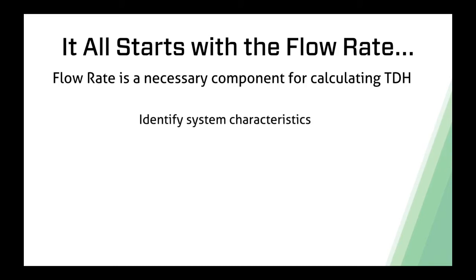We're going to identify the system characteristics. That means knowing what your pipe size is, knowing how much pipe length you have, knowing what elevation you overcome, knowing what fittings you have. So identify all of those system characteristics.